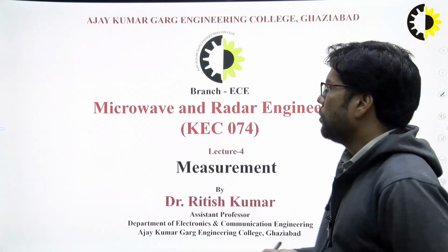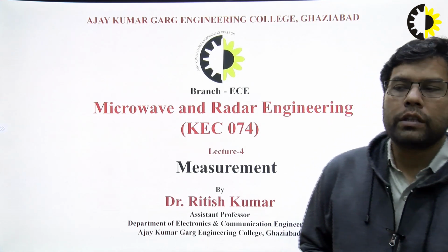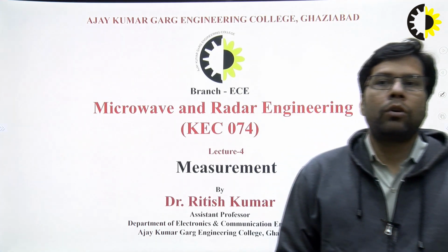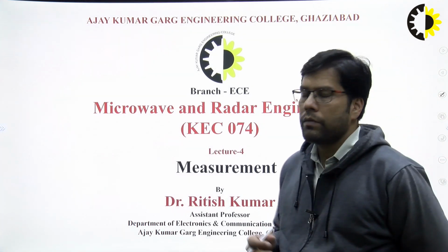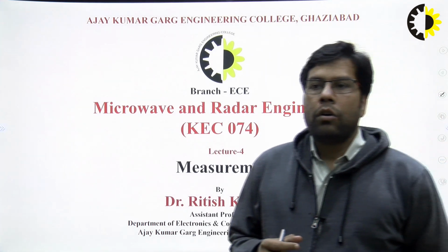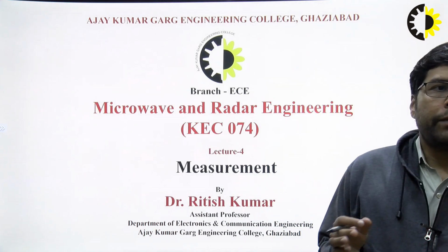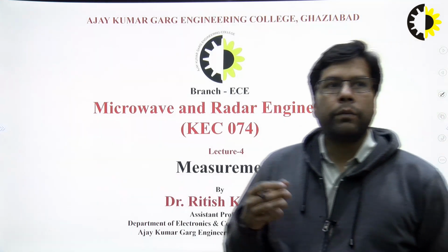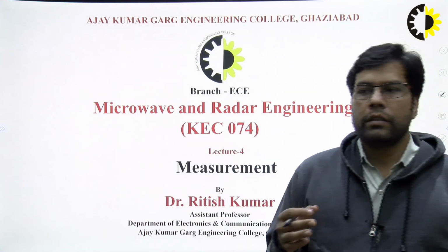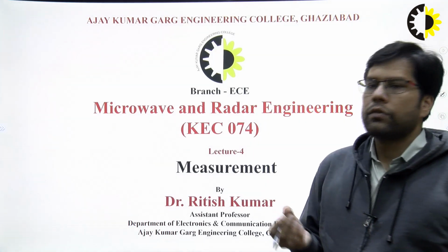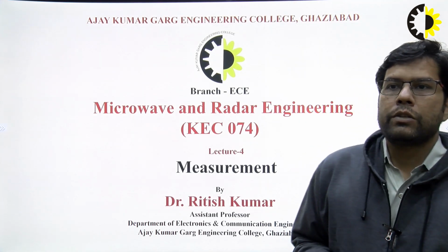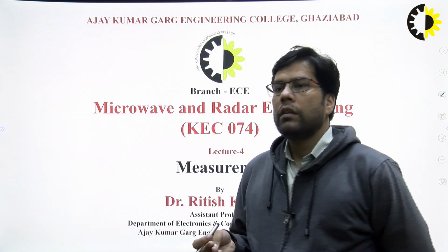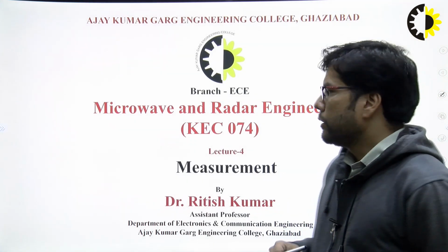What is the VSWR? VSWR is nothing but voltage standing wave ratio. I presume that you are all aware of the microwave test bench setup that you have seen in the laboratory as well. The sequence of the microwave test bench setup is: first the klystron power supply, klystron tube, isolator, then a variable attenuator, frequency meter, then slotted section, and then detector.